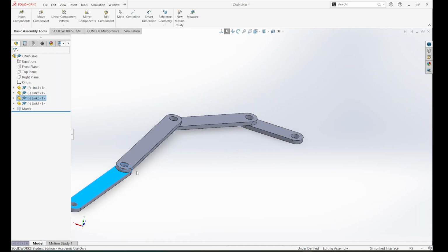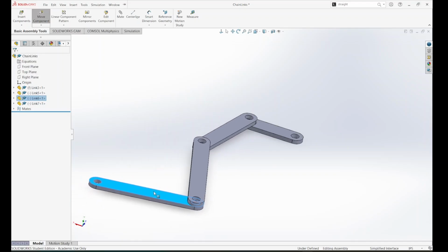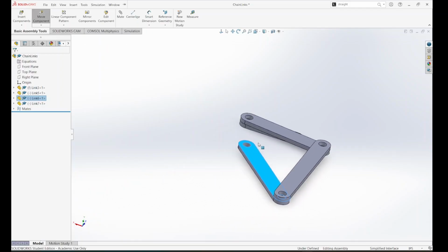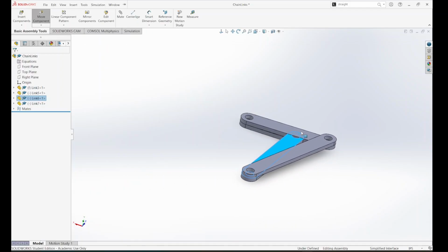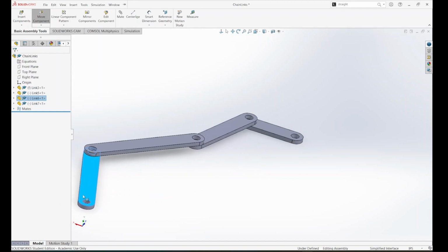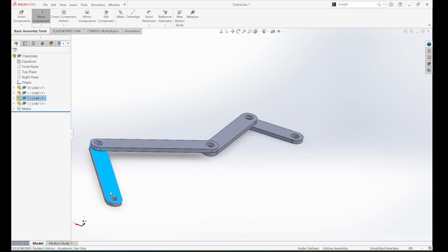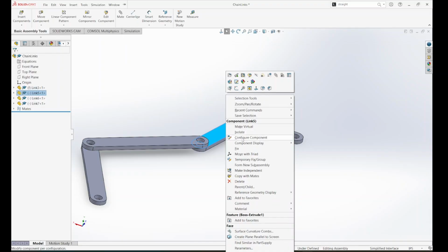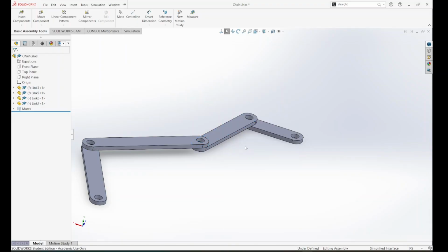So now here's actually a little pro tip. Sometimes if this is crooked, as in if I tried to link these two right now, this edge would snap here and we would get stuck in a weird mess here. What I can do is actually change which link is fixed to help us get a cleaner attachment. So let's go ahead and fix this 5-inch link.